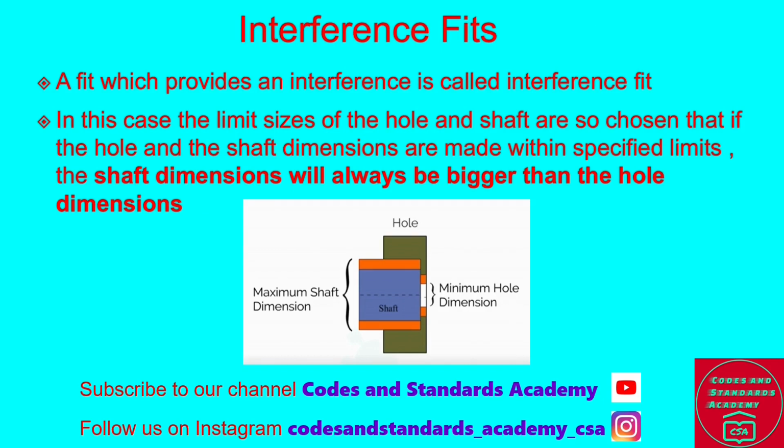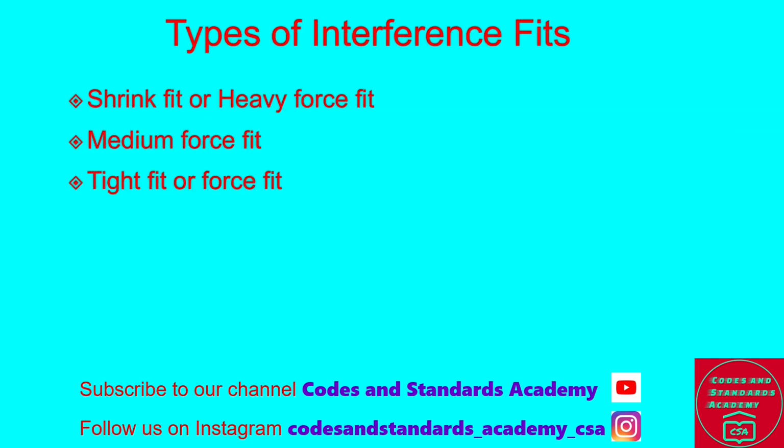Interference fits. A fit which provides an interference is called interference fit. In this case, the limit sizes of the hole and shaft are so chosen that if the hole and shaft dimensions are made with specified limits, the shaft dimension will always be bigger than the hole dimension. Interference fits are of three types. One is a shrink fit, medium force fit, and a tight fit.